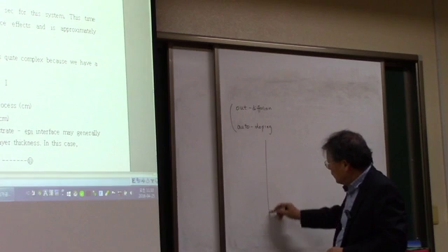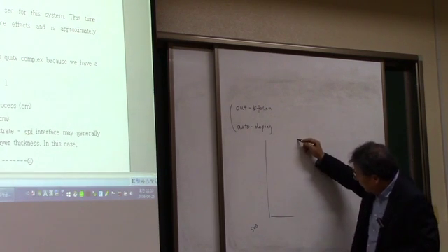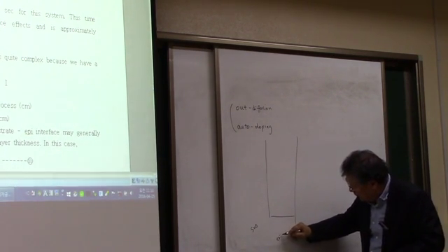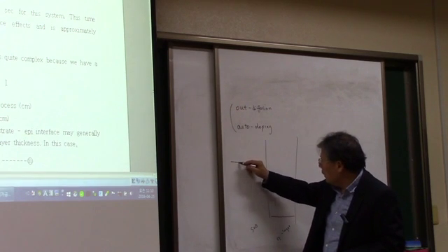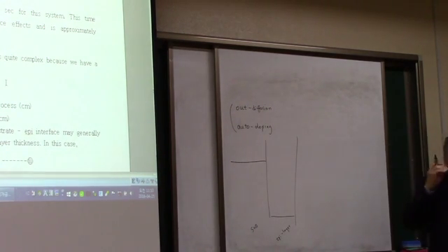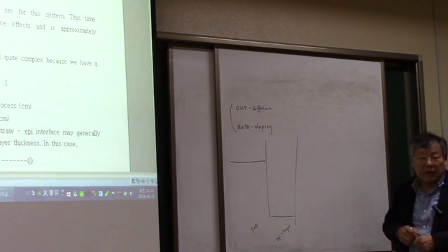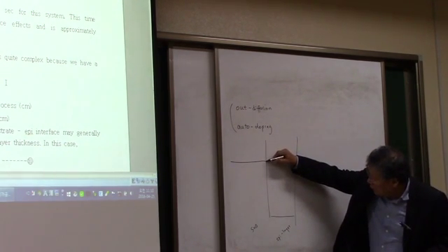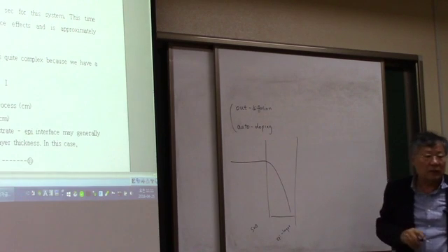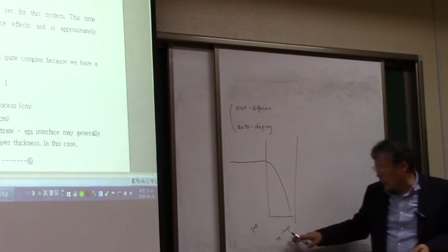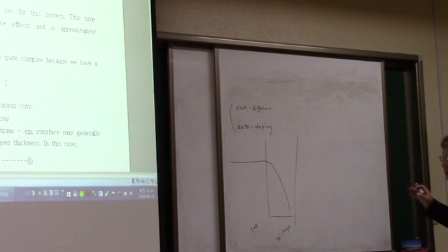Out diffusion is the kind of thing where this is a substrate, and let's suppose we have this thick epitaxial layer. Let's suppose the substrate has a dopant concentration at this amount, and then you grow the epitaxial layer, and everybody can expect that the dopant atoms in the substrate may out diffuse to something like this, because we do the epitaxial layer at elevated temperature, like 1100 to 1200 and so forth. Okay?